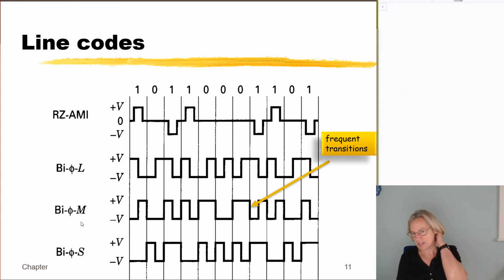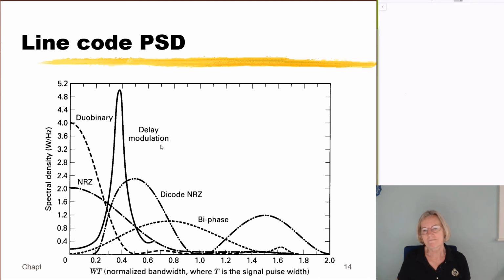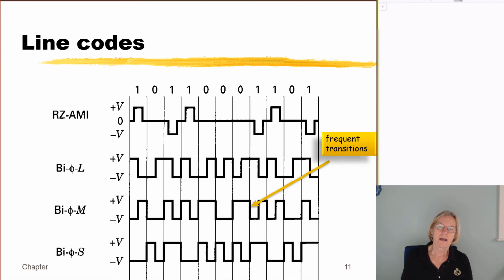Now, why would we want to do this? Well, one reason is if we're forcing a toggle at every bit interval, you would get more transitions. And sometimes transitions are good for locking onto signals. It's easy to see what's going on. So this is one of the reasons that there are so many choices, depending on what are the impairments or the imperfections in the non-ideal components you're using. So that is why we have so many line codes that we can choose from, is to be able to have lots of choices depending on the situation we're addressing.